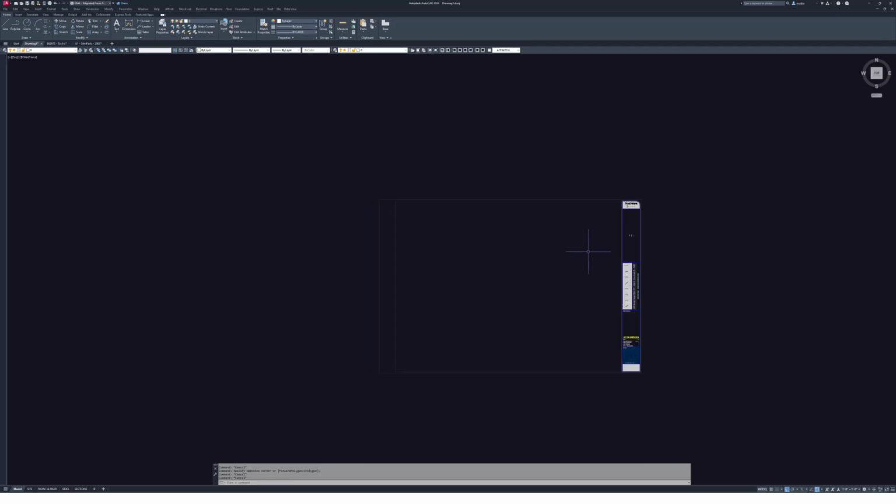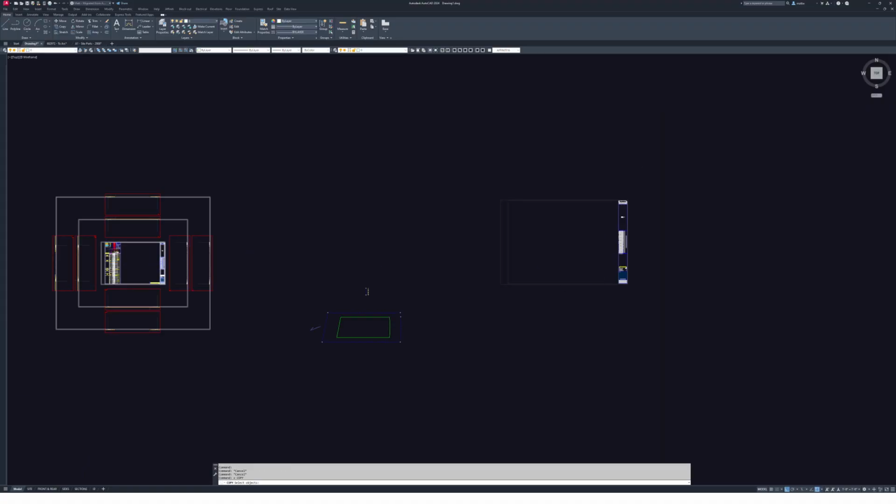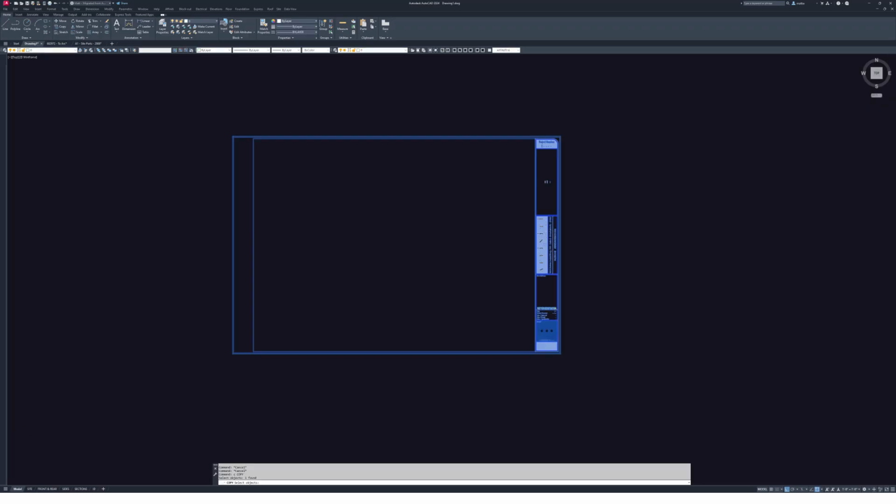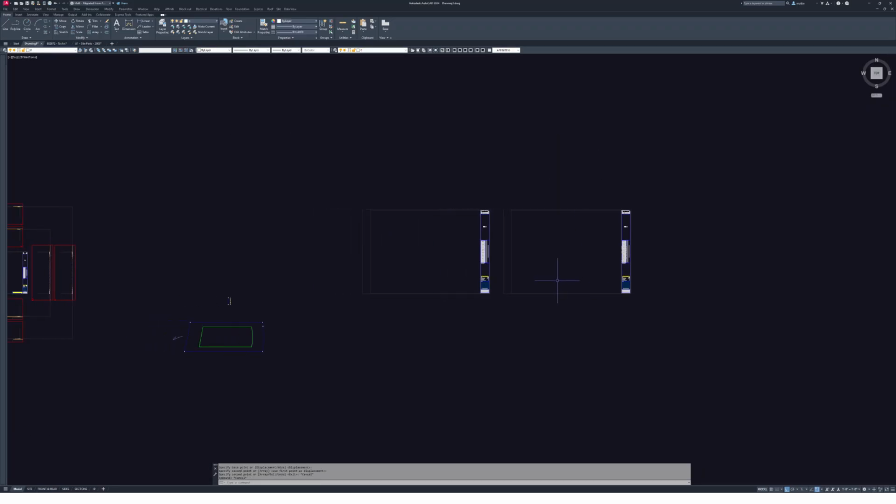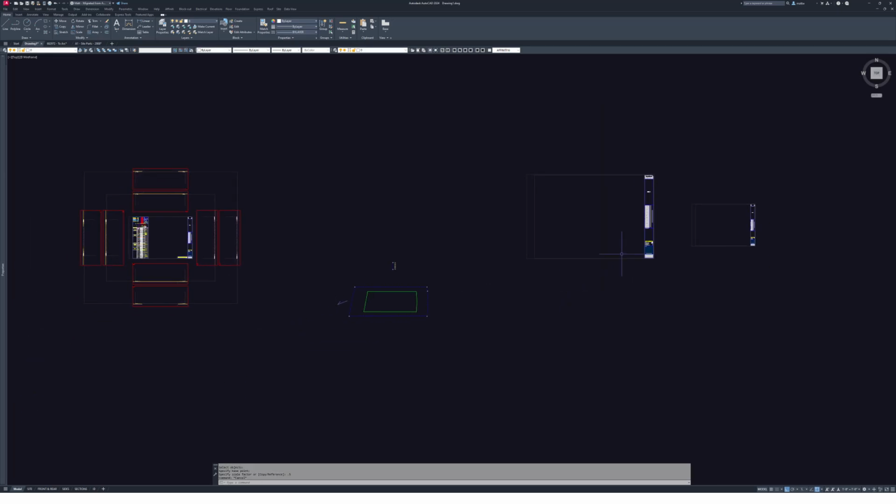And actually I should have waited, because to do a site plan, these sheets, I don't tend to work in paper space. I tend to like to work better in model space, and so I create my page layouts in model space. This is set up to print at 1/4 inch, so I actually just need to scale this up by 2. And so you can see this is my 1/4 inch paper, which makes this one my 1/8 inch paper because it's scaled up by 2. I'll just scale this one back down by half just so I have a 1/4 inch one there as well.